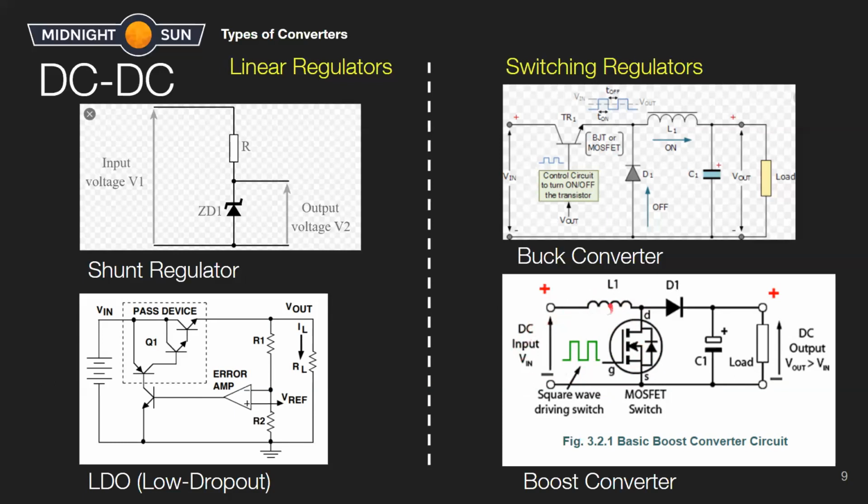So if we imagine this inductor having the voltage or the potential to output a similar voltage as the input, we're basically getting double the power. And so this power then goes through to the load. It's getting charged from the capacitor again to smoothen it out, and we get this kind of circle. But we see that the amplitude of our waveform is higher than the amplitude of the input voltage because of the inductor, and so we get a boost in terms of the RMS we're seeing.